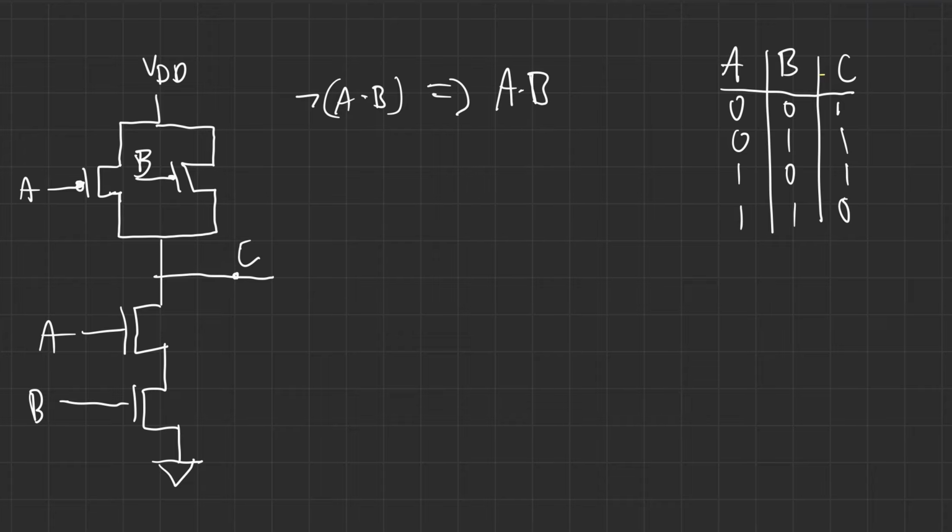Well, maybe it's kind of obvious. You NOT a NOT. Logically, if you NOT a NOT, they cancel out. And this is kind of why it's Boolean logic, but boom. So all we have to do is NOT this. So we have to put an inverter. Well, we have to do it with a CMOS circuit, so I'll show you how to do that.